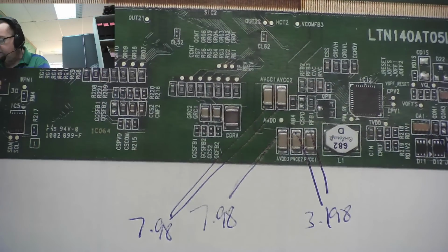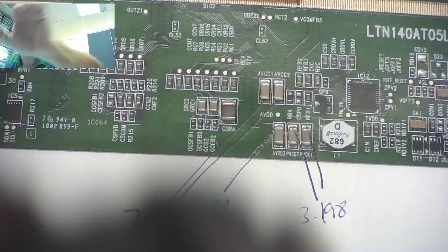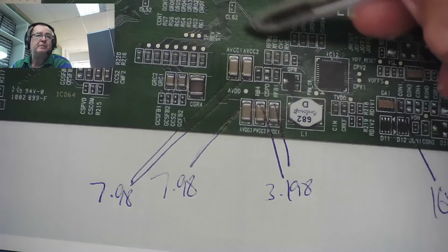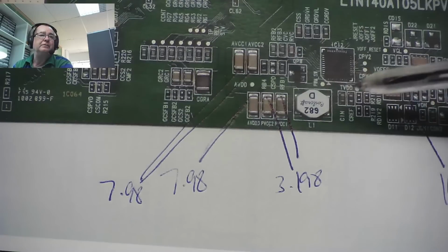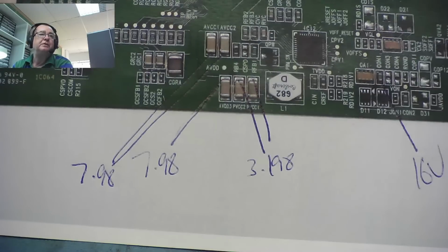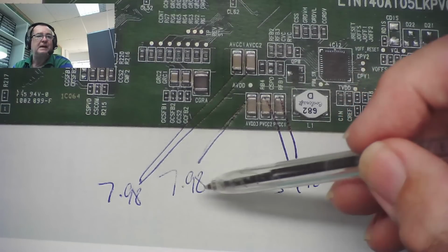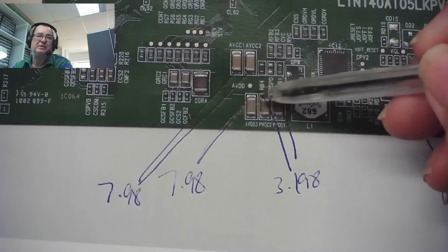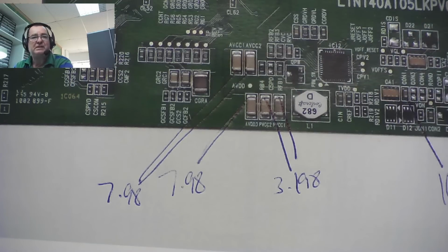Okay guys, that was quite a worthwhile exercise actually. There we are. I checked it on these capacitors because these are in the region of this coil, and generally in the region where we found one of the voltage test points as well. So I had a look at these, and we're getting 8 volts here, which we know now is this AVDD. In fact, the test point is there anyway. These capacitors have 3.198 on them, and they're the same in both panels.